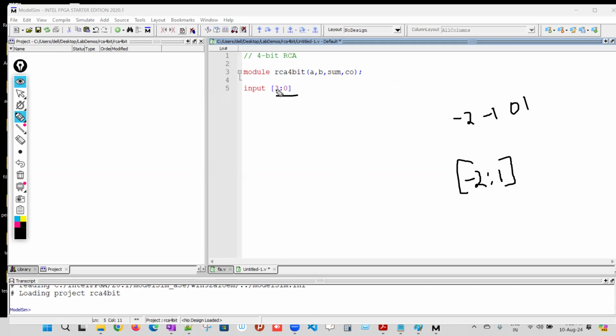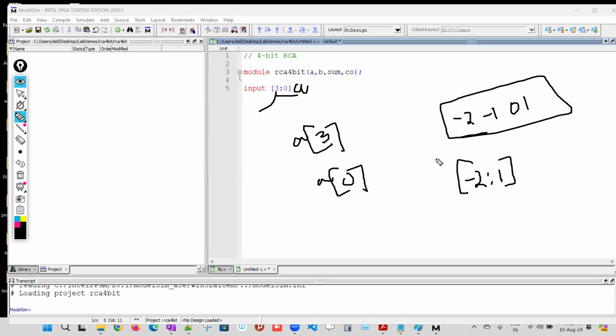This approach, one can easily remember, like, this is the MSB side. So the moment when we tell this is a 4-bit, then anyone can guess whatever the variable is here. So A of 3 is our MSB, A of 0 is our LSB, like that. But if you prefer some other ranges or indexes, then that leads to confusion.